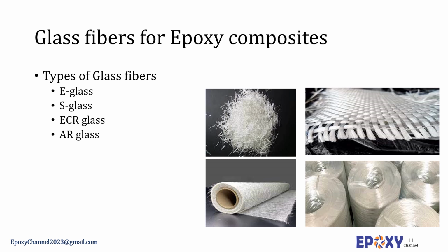Some manufacturers use polyester epoxy resin film formers for compatibility with a range of polyester and epoxy resins. Fibrous mat or reinforcing tissue will have an additional polymeric binder, which can be selected to control the wet out of the fibers in the chosen fabrication process. The adhesion promoter, which is generally a silane coupling agent, is expected to generate a strong interfacial bond between the fiber and the matrix.